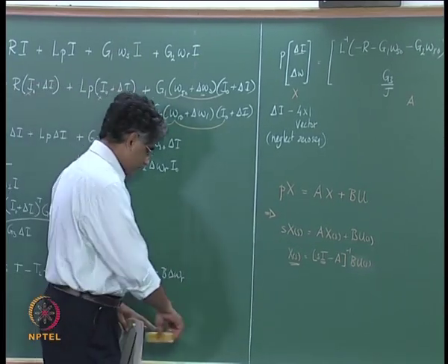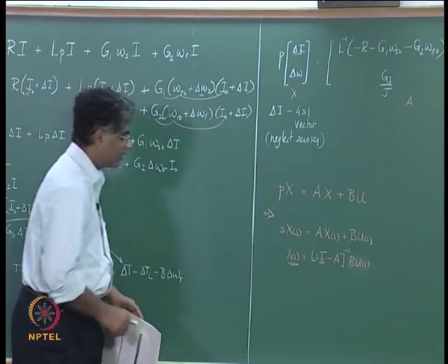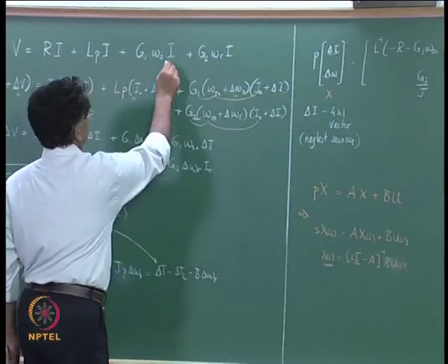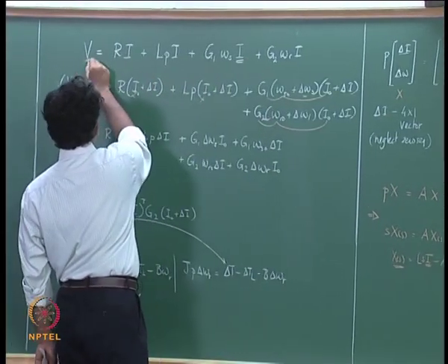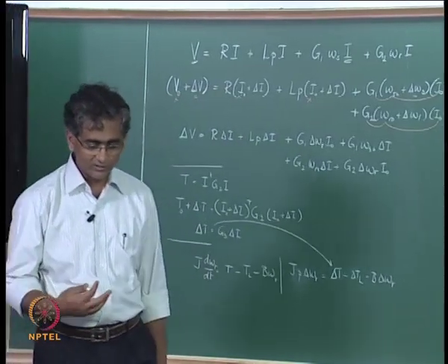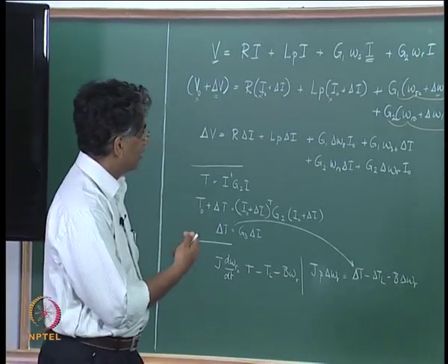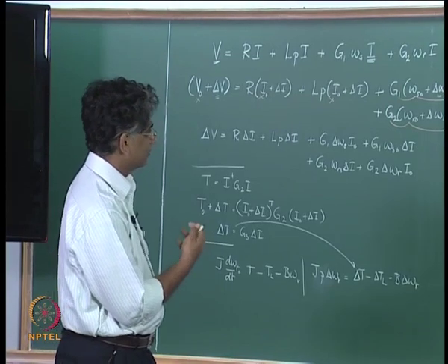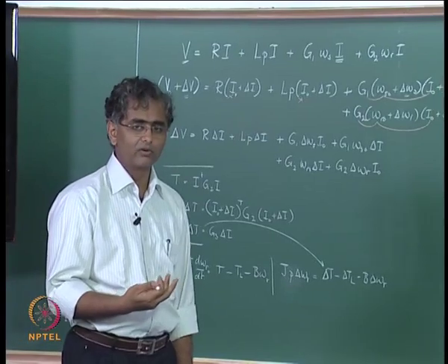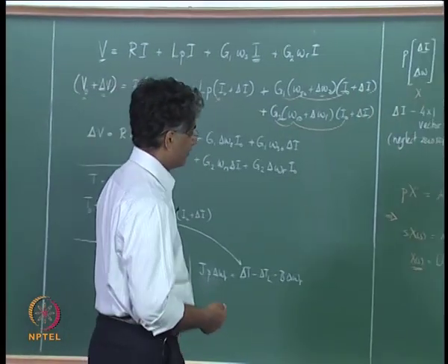In this reference frame, the advantage is that all the variables here, that is I and V, are basically DC. So as far as the equations are concerned and the way you use those equations, all these variables are DC, and therefore it looks similar to a DC machine from that viewpoint.